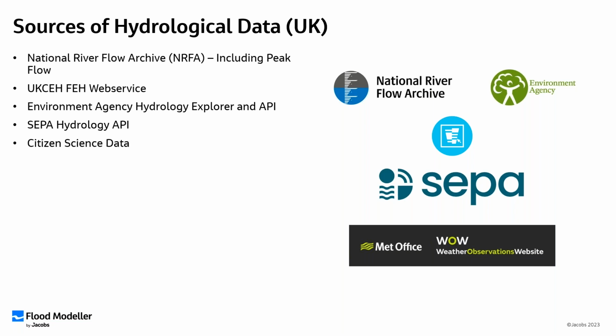And that for a long time has been accessible via our website, but is now also accessible by an API. So you can connect directly into that. So you can connect Flood Modeler to that. You can connect things like Python or R, so you can create your own codes and scripts and analysis. And that's a very powerful resource.